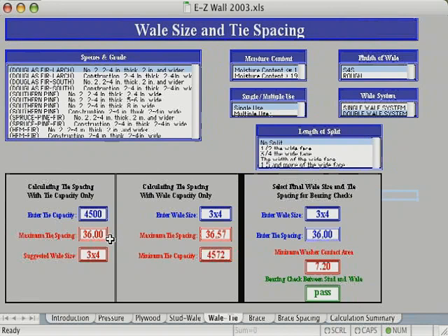That's equation 6-18 in SP4, to solve for the minimum section modulus S required. The spreadsheet then sorts the dimensional lumber table records, table 4-1D in SP4, by ascending S values. The spreadsheet is programmed to perform a vertical lookup and return the piece of dimensional lumber that has the next higher value of S as compared with the calculated minimum required S.